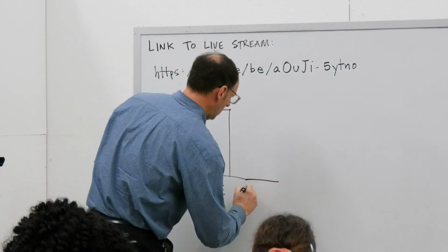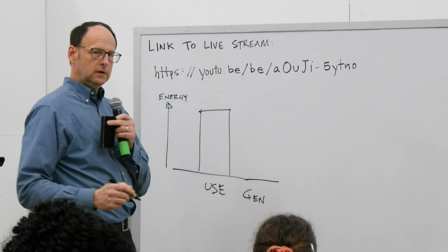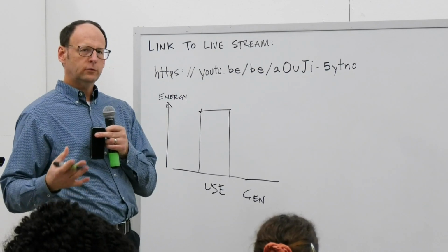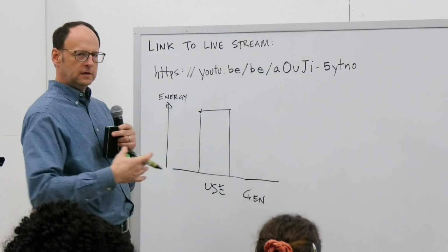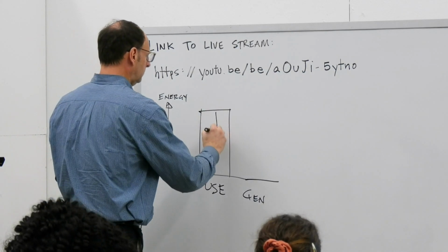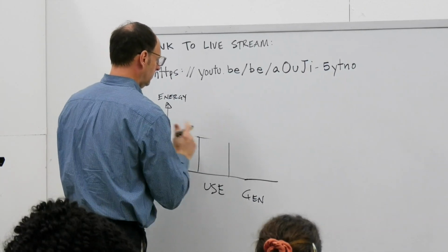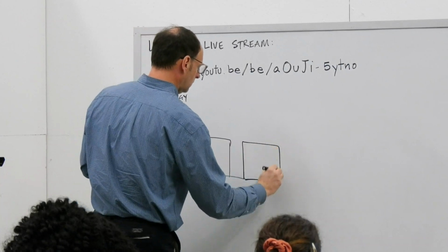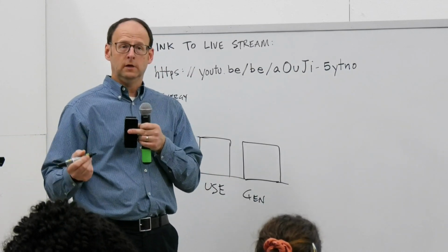And then we have how much the building itself can generate. All right. So in a ZNE building, we want these 2 things to balance. The first approach, though, is to reduce the usage. It wouldn't make sense, for instance, to take an inefficient building and power it with expensive renewables. So we want this to go down. So maybe we have a reduced energy use for our building, right? And then we're going to match that with the amount of power the facility can generate in a year.